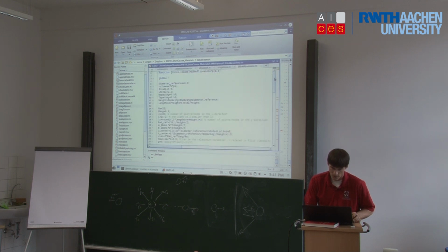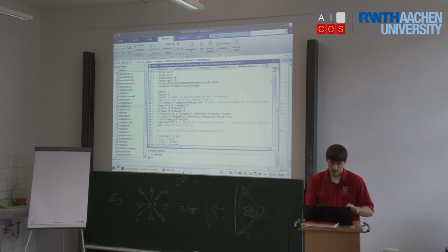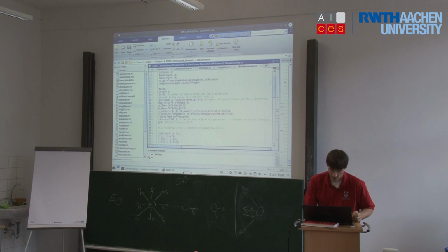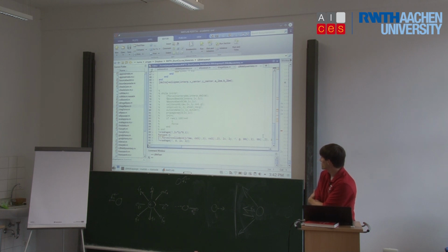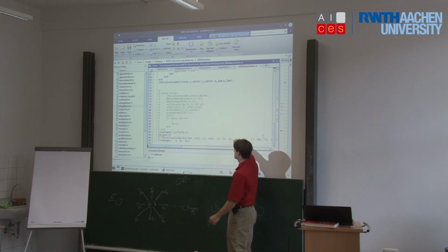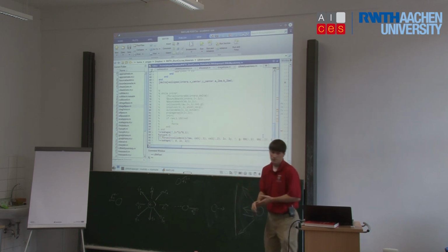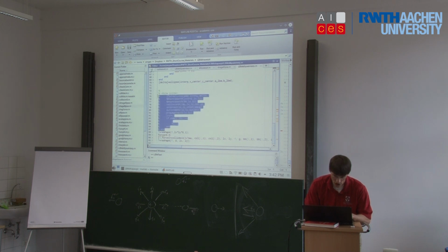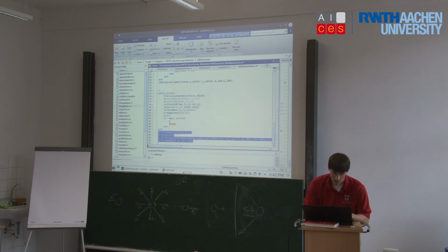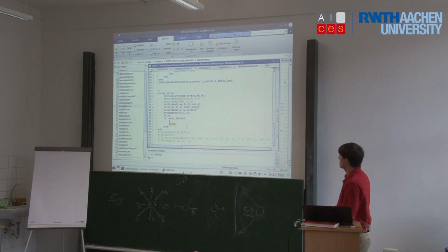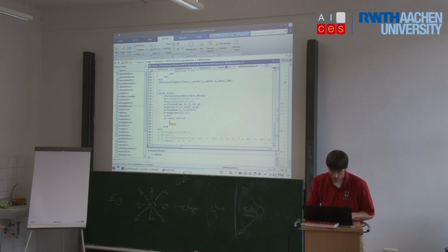And it then uses the Lattice Boltzmann method. It sets up initially how big is my mesh, how many points am I using in each direction, which points are boundary points, which points are interpolation points, which points are inlet, outlet, and collision points, and then it solves the problem right here with, in this case, the C implementation of the Lattice Boltzmann method. But I can go in here and I could change this and uncomment, comment, and then now I've changed it from using the C implementation to using the Matlab based implementation.